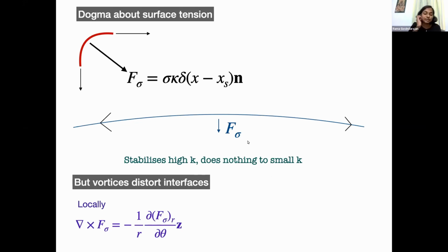Of course, it will still do this, but it will compete against itself. So how does that work? That's because the vortices themselves distort the interface. We saw that a straight interface is quickly wrapped into a spiral. Namely, the interface is made longer by the action of vorticity. So the interface is made longer, and surface tension doesn't like that, but it can't just reduce it like this. Because it generates vorticity along the interface in this fashion, it can't merely reduce the surface area. It can actually generate this instability via generating vorticity.